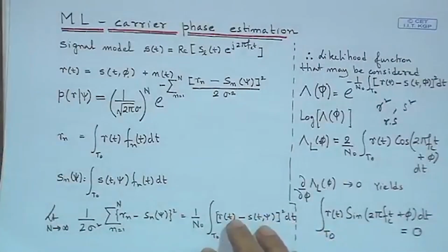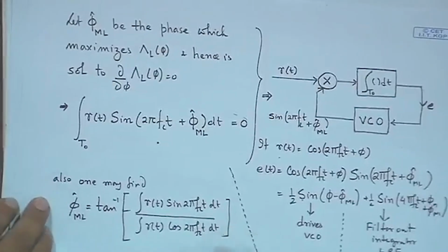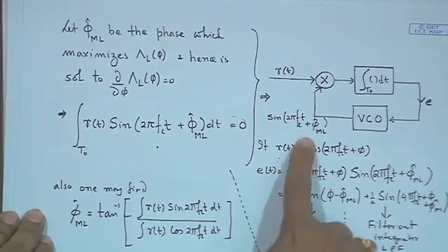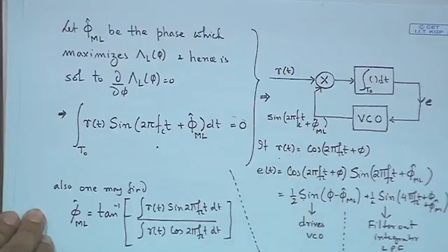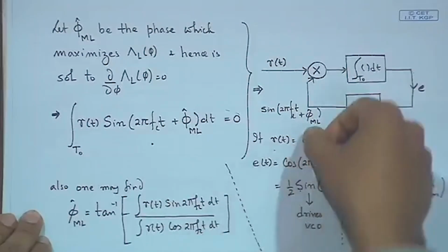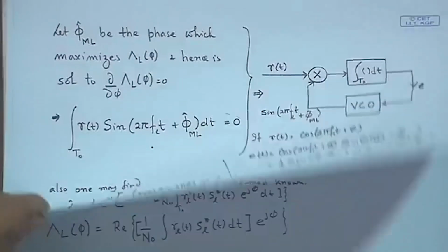In all the previous cases you would have seen that we have taken the received signal as cos 2 pi f c t. Now, there will be A in front of it. If there is an A in front of it, the integration output that you will get is going to go haywire, because the modulation A in front of it could take plus and minus values, and the integration could result in a 0.